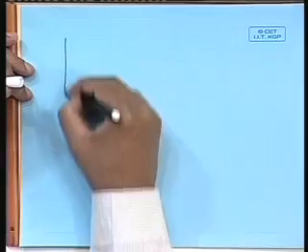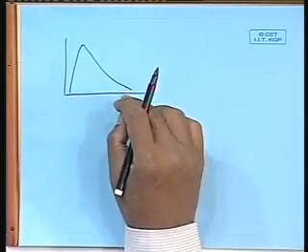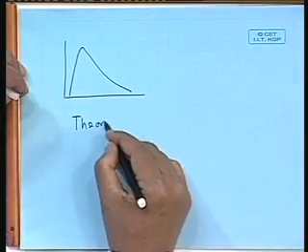Now comes the second question. We are engineers, we cannot keep going and measuring wave heights at every point. What we need is somebody to tell me, look, I have a ship going from here to the Bay of Bengal, what is my weather at the Bay of Bengal in terms of a spectrum. So what people have done is that the oceanographers, who have been doing wave modeling and all, came up with what is called a theoretical spectrum.